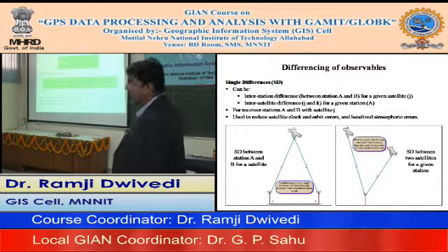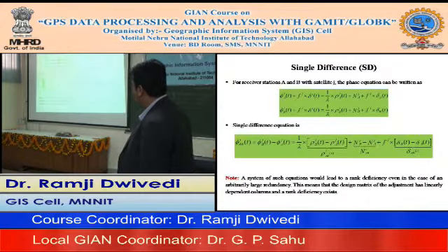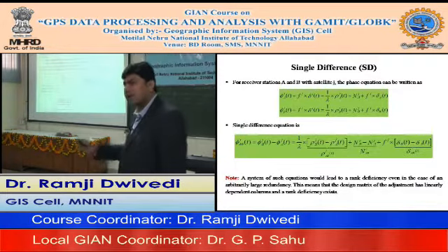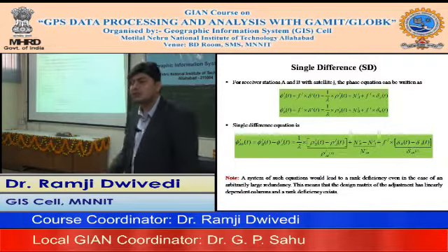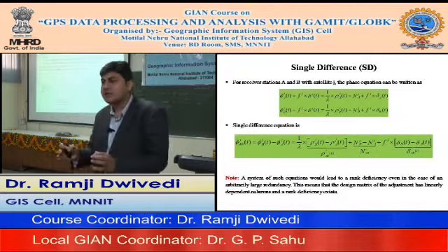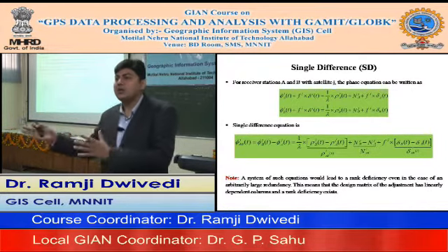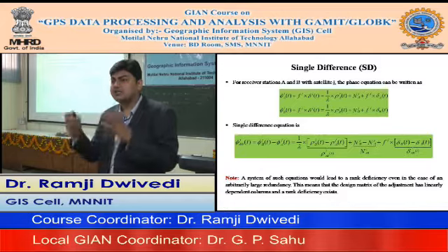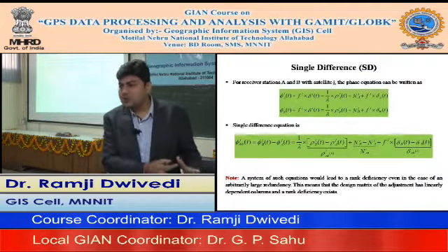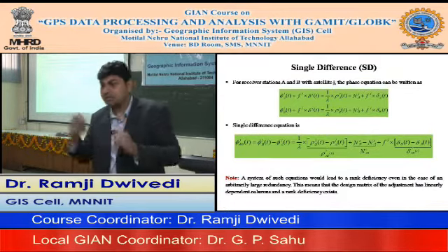Eventually we are not interested in this part, instead we are interested in this part, because we have 1 base and 1 rover. If you are not familiar, the base is a station which is properly fixed with respect to your relative measurements. You generally fix a base station near your site if you don't have access to other base stations.